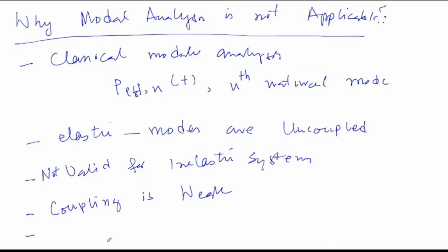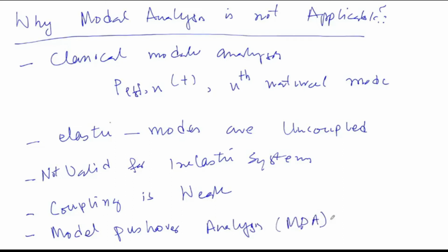And this is what permitted the development of a procedure called modal pushover analysis, the MPA procedure. We will talk about this a little bit. It is a procedure used for static analysis of a structure to predict the dynamic response of the structure in a simple way.